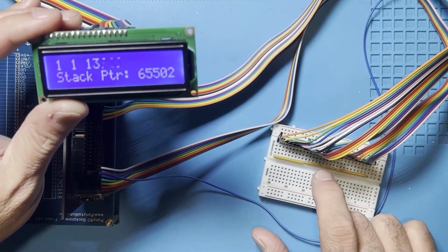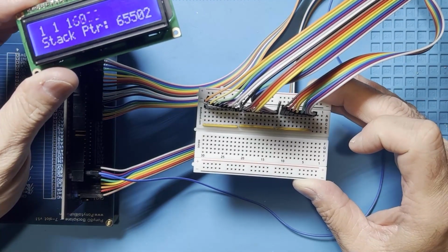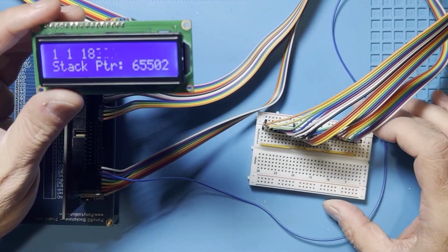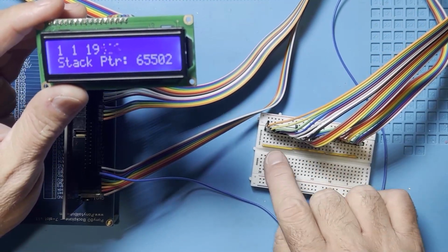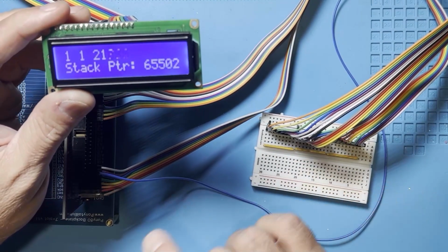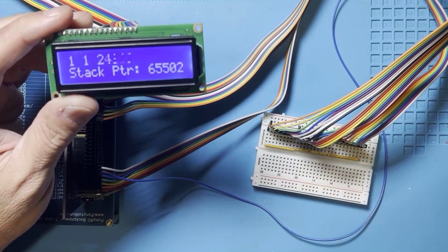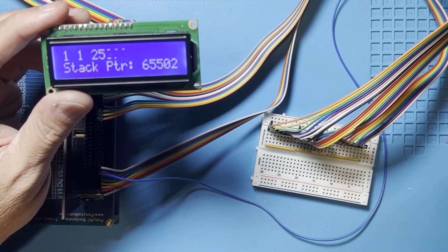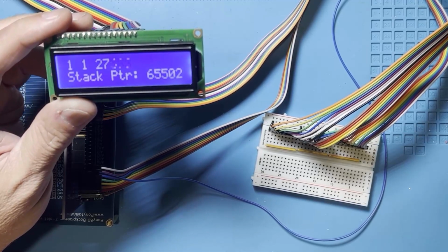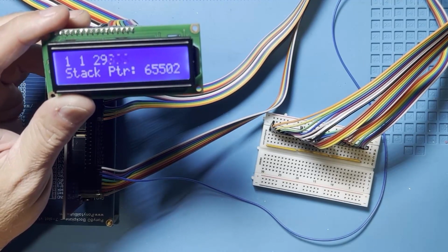So we've had to ground all of the data and address pins, and I'll probably maybe here in a few minutes just experiment with removing some of these to see if it's one or the other. But I also want to take a deeper look at the cards and see if one of them could be causing a floating address or data pin, and get that fixed up.